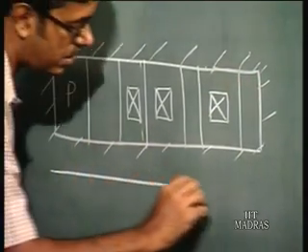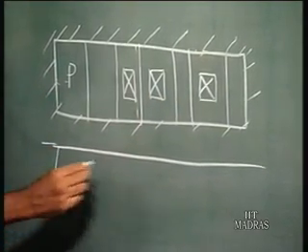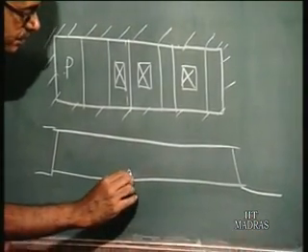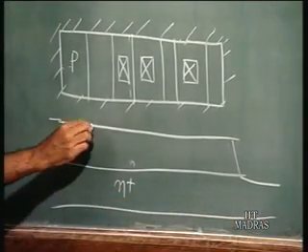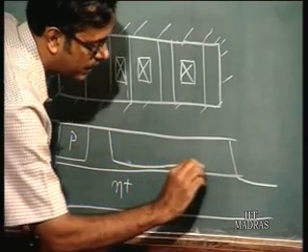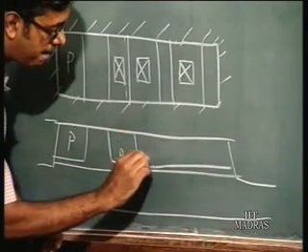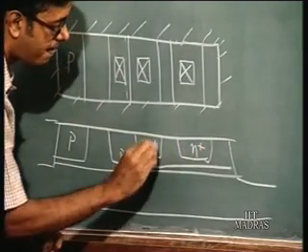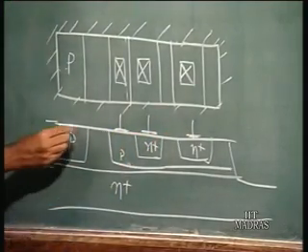So basically, if I draw the cross section across this region, you have oxide, silicon dioxide. So this is N, this is N plus. You have the P wafer. This goes all the way. This is the base region. This is the collector, and this is the other collector. So this is the device. I hope it is clear.